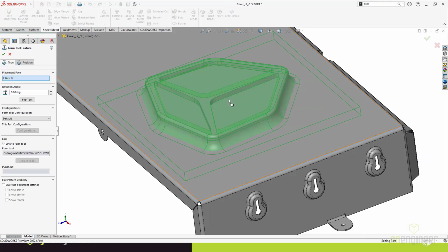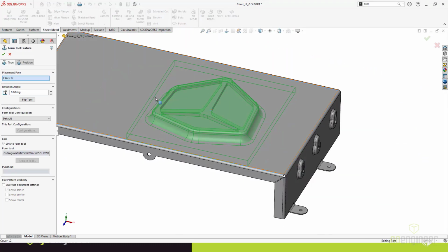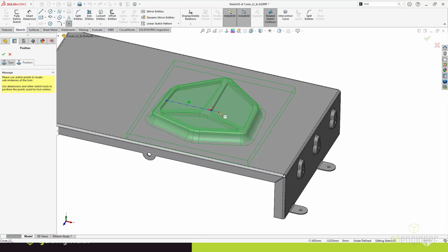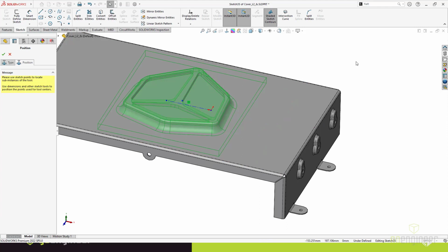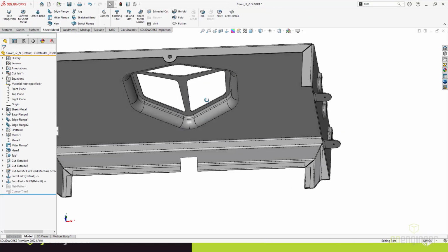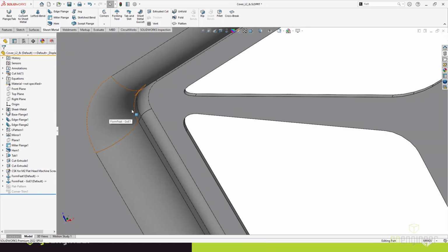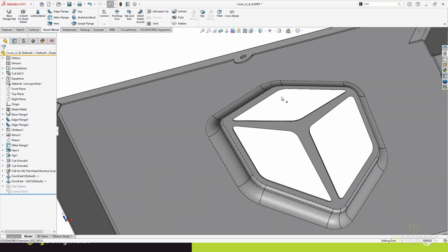And once that's in place, really it's just a matter of either dimensioning this feature if you need to. Sketches will allow you to go ahead and dimension that with the position tool, or you can go ahead and add additional ones through, again, clicking additional points. But placing that is no more than just dimensioning sketches. The result of it all gives you this wonderful embossment. Once again, it's going to go ahead and take the thickness, and it will take the radii and roll those up as if this forming tool that we had sits right on the inside of this cavity. So again, whatever that thickness is, it grows independently outward from whatever the form tool happens to be.